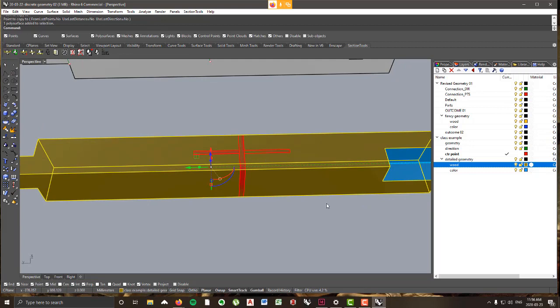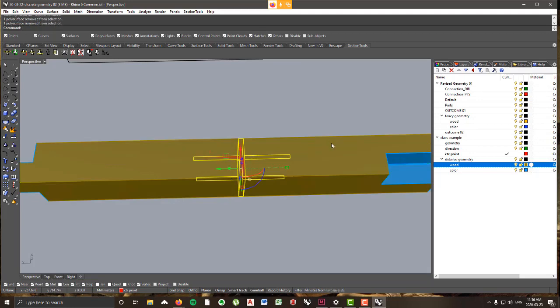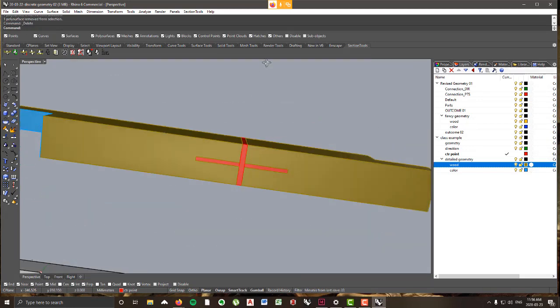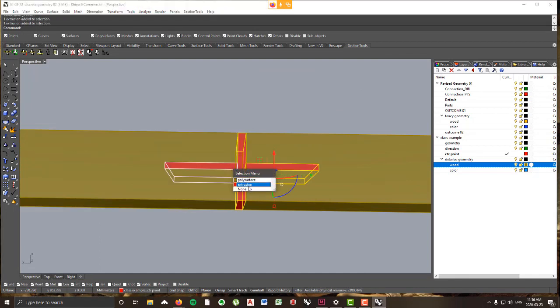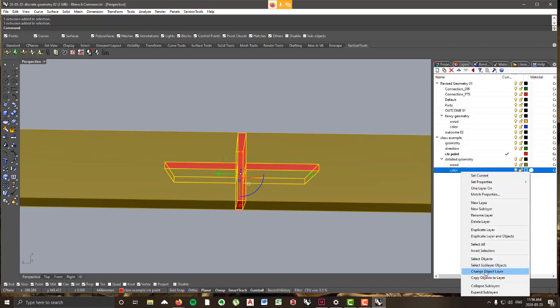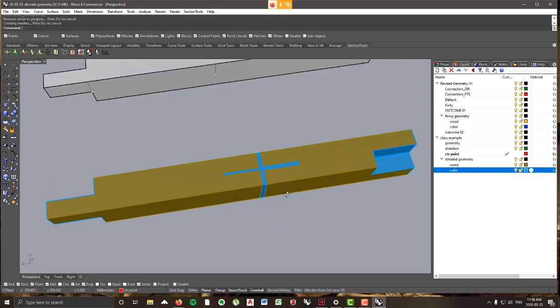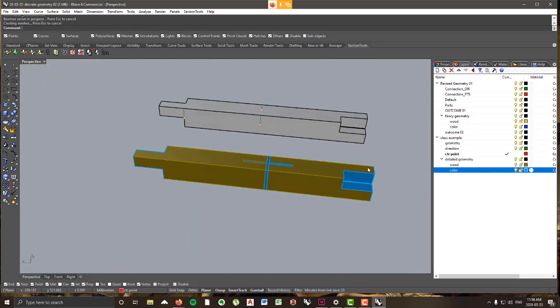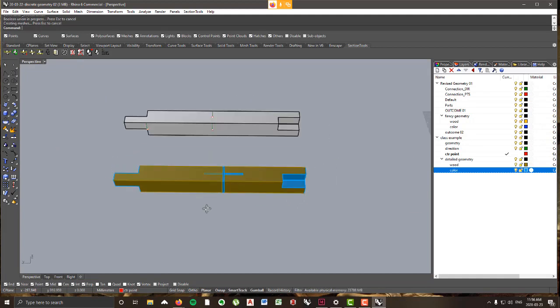neat looking. So I'll select my wood surfaces, I'll click split, I'll select the B-rep that I just made, I'll deselect the parts I want to keep. I have kind of this cruciform shape here, and I will change this extrusion to the color layer, and then I'll just go Boolean union to create a solid shape. So this is my more complex version of this shape here. Again, it doesn't matter what you really have, but this is the more complex shape.